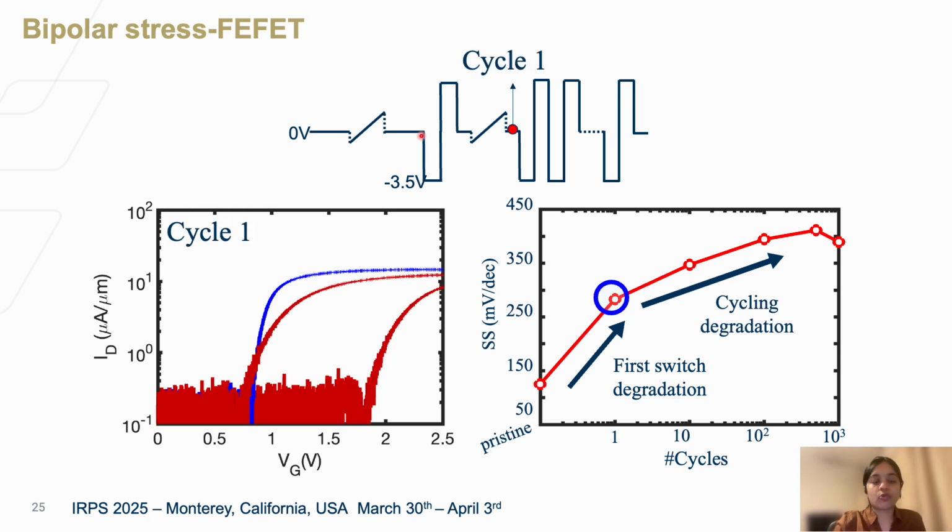Now, let us apply one particular voltage pulse to this device. So we apply one cycle to this device and then perform the same read operation. That now gives us the memory window, because we're performing the read operation in the positive and negative direction, that is, with erase and program pulses. So that gives us the erase and program states with the memory window.